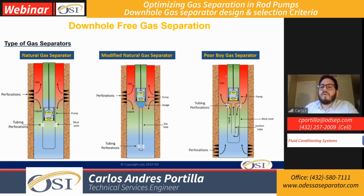And then we have here our poor boy gas separator. The poor boy gas separator was developed because in this case we need to install the pump above the perforations. Basically, we're forcing that liquid to travel through an inner annulus we're creating with our gas separator. Every unconventional well will be this case. Many companies install the pump in the vertical section, and as you know, all the perforations are in the horizontal, in the multiple-stage fracturing. So this will be the case for unconventionals.